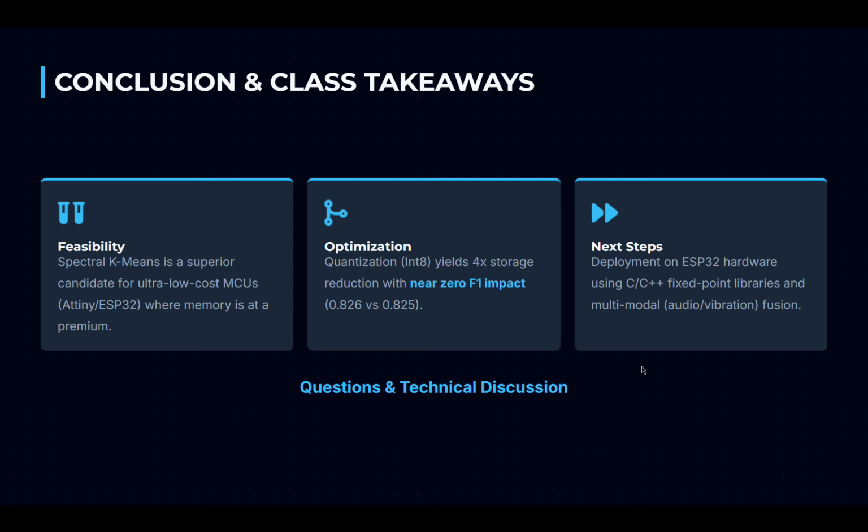It had some strong detection performance and only required a few hundred bytes of storage. So it's pretty practical for a low-cost embedded system, and reducing the model by about 4 times through the design process had almost no impact on accuracy, which is a very interesting takeaway, and just goes to show that TinyML is a suitable application for this.